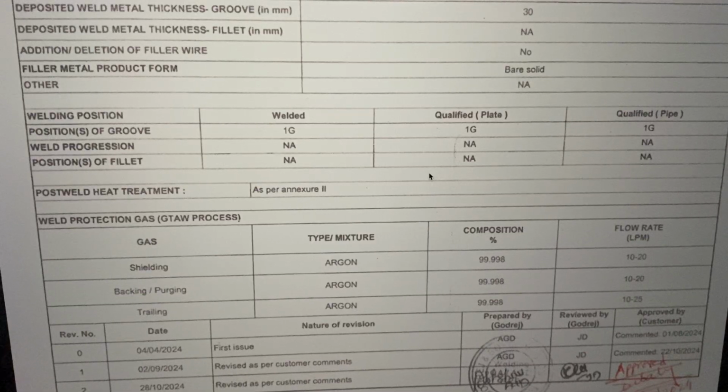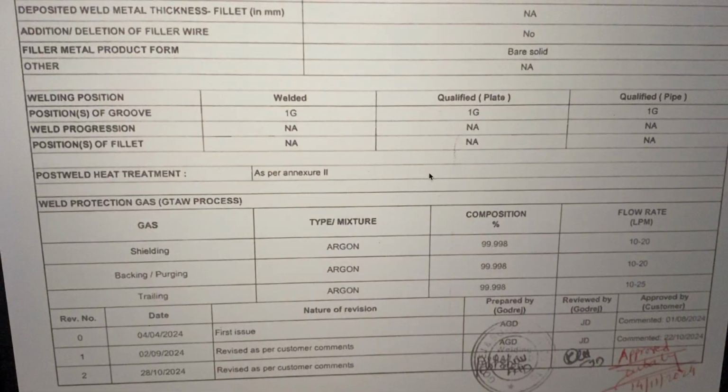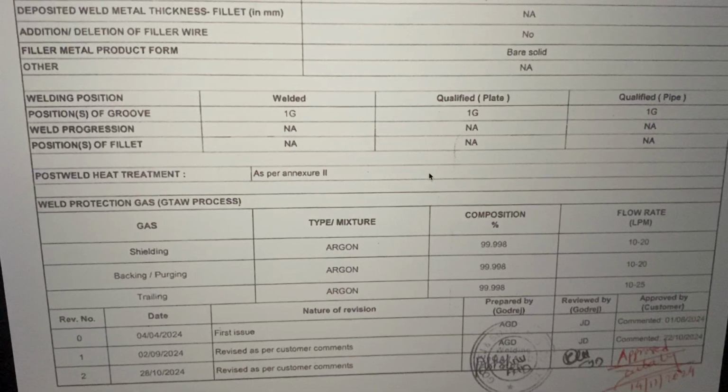Like for a carbon steel, alloy steel, martensitic ferritic steels, or even sometimes for titanium alloys, it becomes essential to drive away all the dissolved, soluble gases in that particular material, and especially the hydrogen, which is the tiniest gas and can move even at room temperature and gets accumulated in the cavities, porosities, or any metallurgical imperfection, and can create a higher pressure and create a small notch from this.